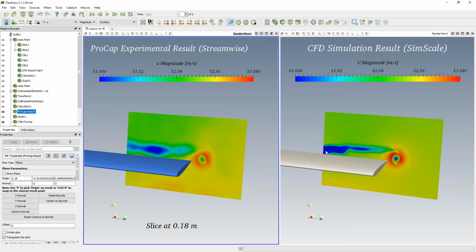Slight changes in the flow you see close to the trailing edge which is away from the tip. This can be due to the different nature of the flow based on the experiments. Because the simulation is entirely done in turbulent flow regime, in real life we can have a transition or a semi-turbulent flow, and this can cause a little bit of differences compared to numerical simulations.